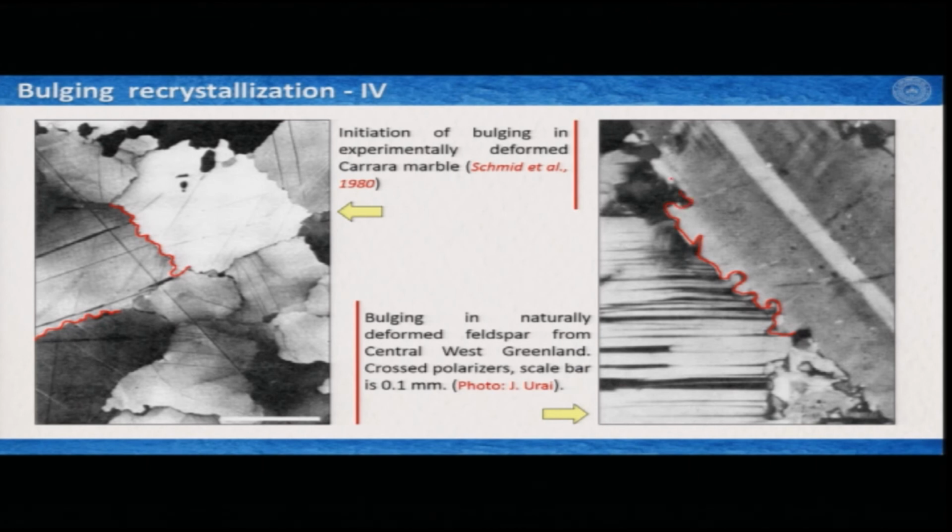So, if you see a thin section or microstructure, now you will see it in a different way, I believe, and you can try to figure out what kind of recrystallization has happened. If you see some sort of little notch or little bulge from one grain boundary into another, first you must conclude that this is a deformed microstructure, and then you can also conclude which grain had the higher dislocation density compared to the other one.